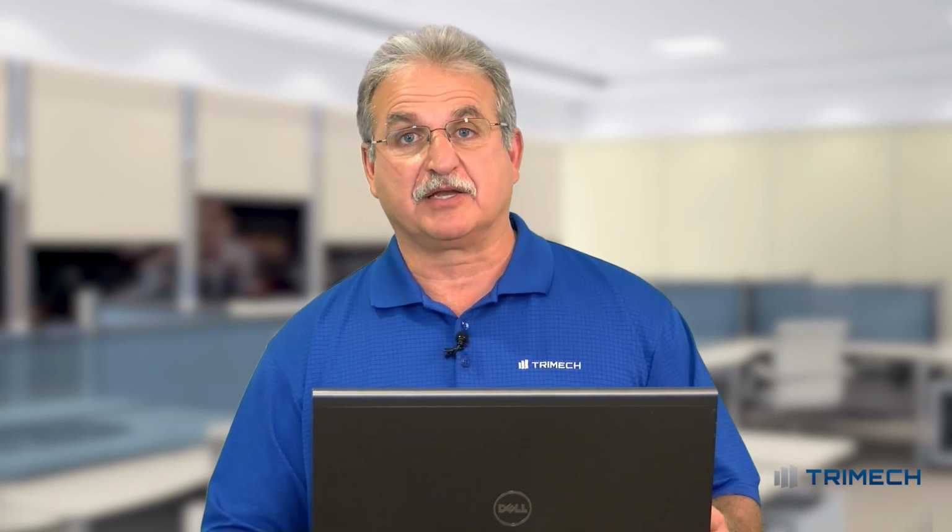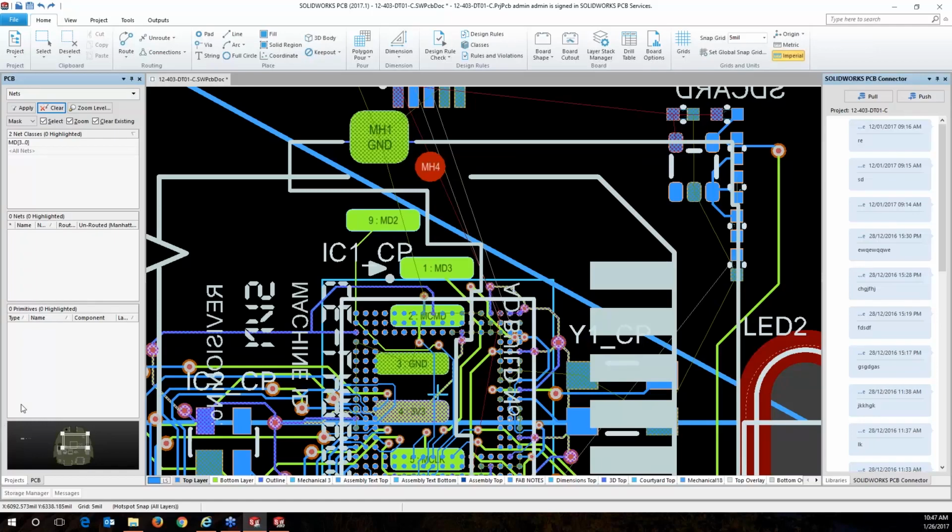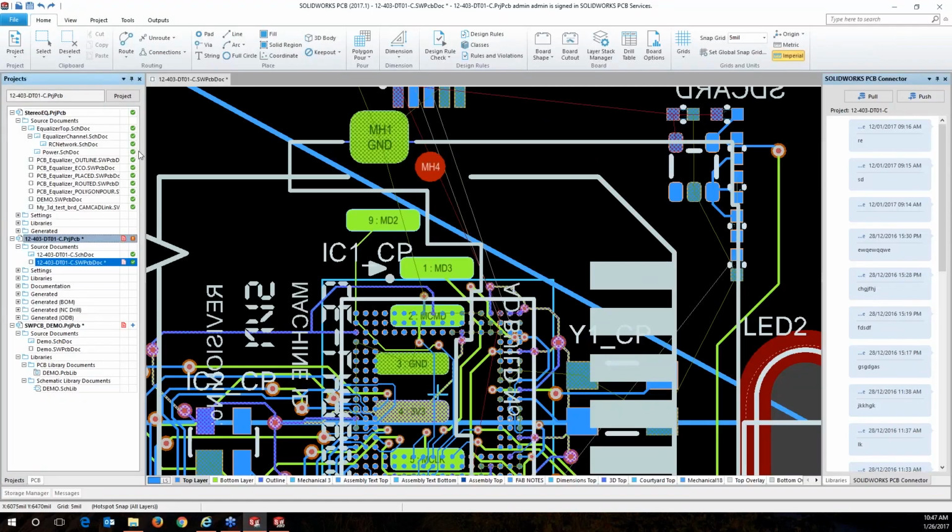But you know what? I think I did some routing earlier on this design that I just want to go back and check. So we have a tool called version control. On the project panel, you notice that I have these little green check marks. That means that all these documents are in version control. But I've been changing this around. And if I highlight this little folder right here, it's going to tell me, hey, this is open and modified. But I have something in version control already.